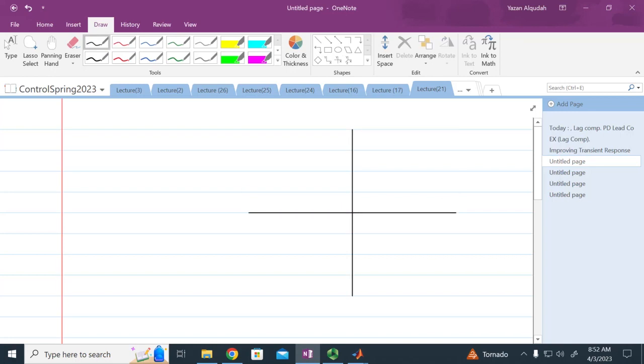If I look at how the system looks, I have a pole at the origin, a pole at -4, a pole at -6, and now I want to be operating at a point that is here, that is -3.63 plus j6.19. Make sense? And this is currently not on the root locus. How do I make this on the root locus?